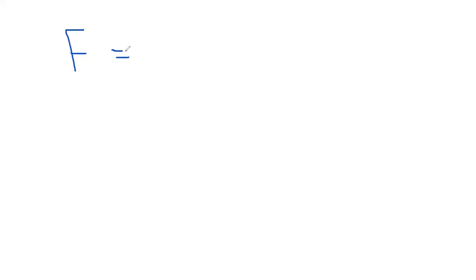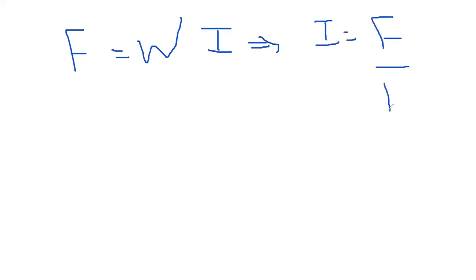We know that F equals Ni, so the current I equals F over N. And here we need to determine the total MMF in order to determine the required current sufficient to achieve this flux density in the air gap.